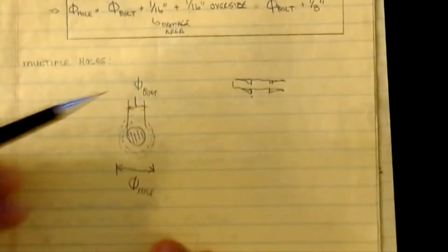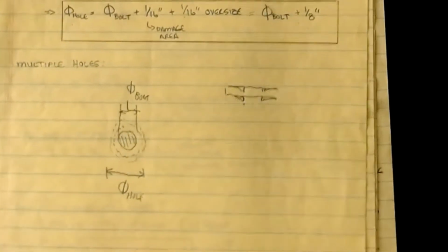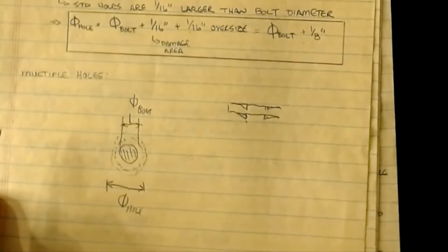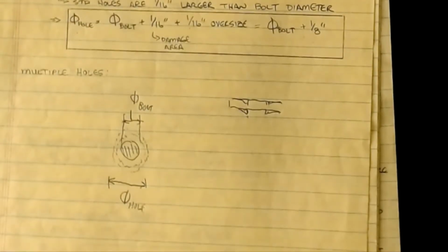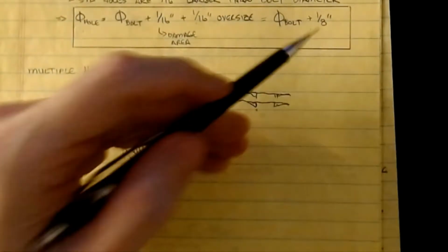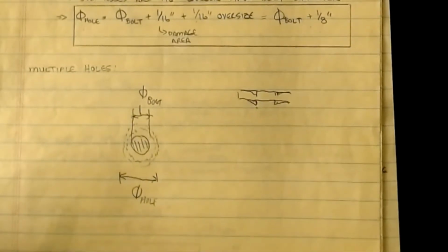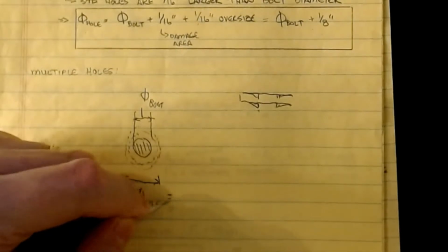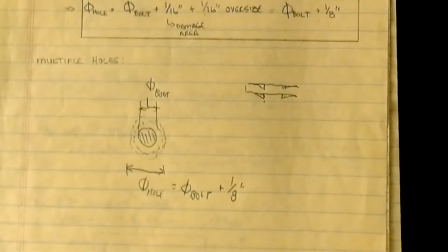And we use a phi value to represent diameters on a lot of stuff. But on a structural drawing, we'll call out the bolt, that it's a 3/4 inch bolt because that's what I need for strength. Then the fabricator knows, oh, well, I can add it and do whatever I need to do. And in my design calcs, I typically add the diameter of the hole as diameter of bolt plus 1/8 of an inch, for pretty much every hole that we have.